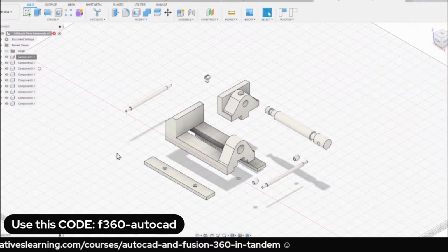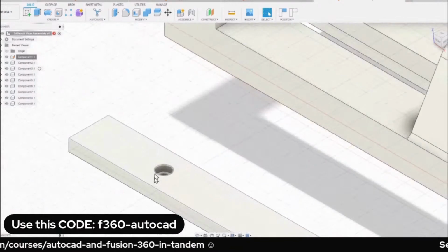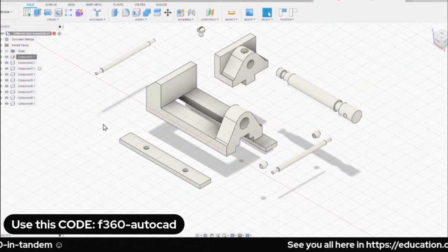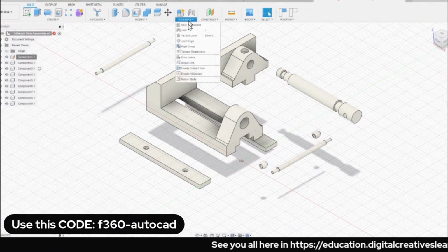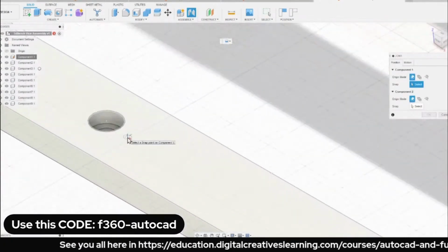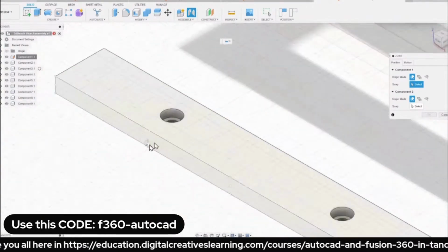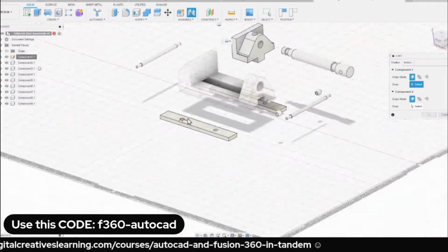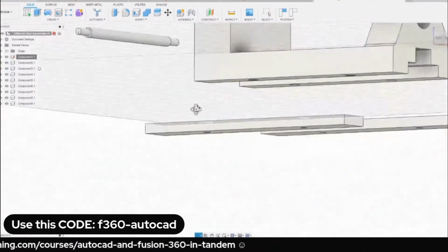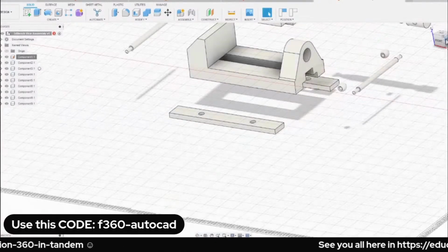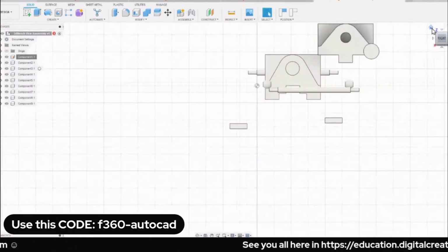So I'm seeing if there's a hole there, it may probably be secured rigidly by a screw. So I'm going up, selecting assemble, selecting joint. And I'm seeing a countersink or a screw with a head. So with that, we can also rotate